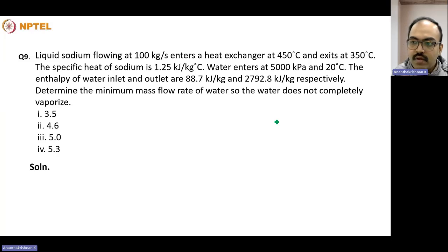So what I meant to say is that if we were to use water and go to 883 degrees Celsius at ambient pressure, it will be in the vapor form, in a superheated condition. But if you pressurize the liquid, it can still exist in the liquid form at 883 degrees Celsius. For that, pressurizing energy is required. Otherwise you would have to exist in the two-phase condition.